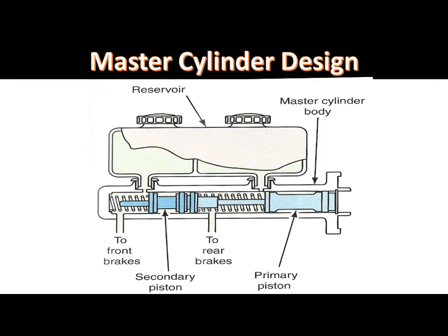This pumping action may cause a pressure drop in the master cylinder because the fluid cannot flow back from the wheel cylinders or calipers as quickly as the master cylinder pistons can move when the brakes are released. When the pressure drops in the master cylinder, atmospheric pressure on top of the fluid in the reservoir forces fluid past the cup seals into the piston bores.